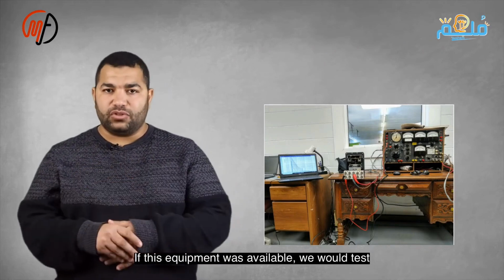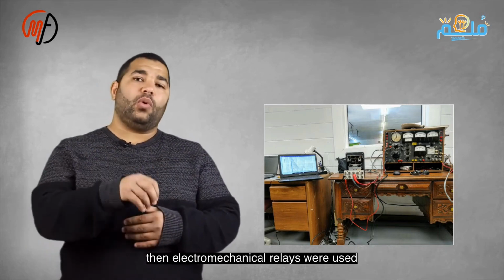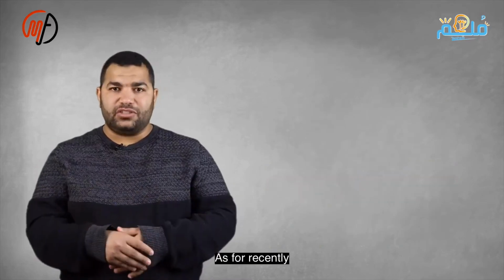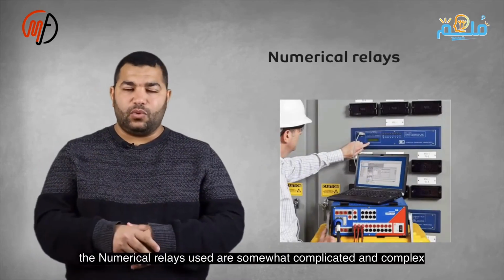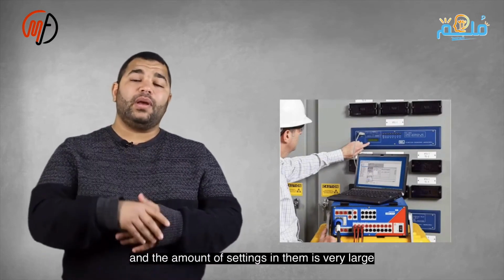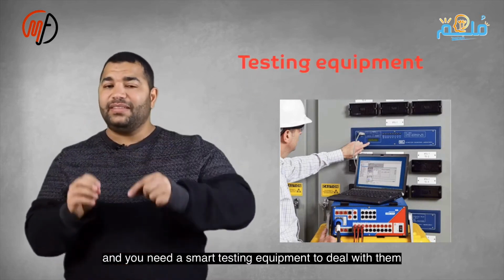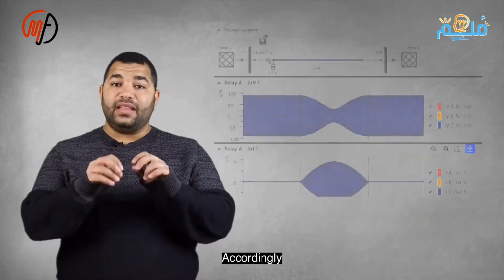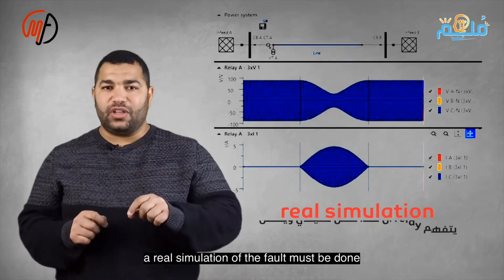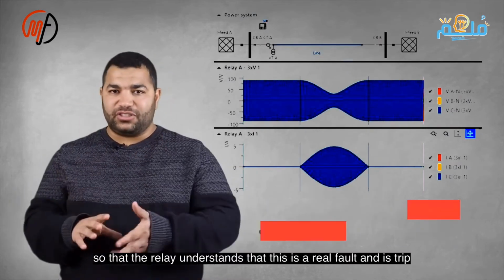Now, new numerical relays are smart and complex, requiring advanced testing equipment due to numerous settings. Real fault simulation is crucial for relays to recognize faults and disconnect. Without this, relays may stay energized. Engineers unaware of numerical relay stages might find relay behavior unpredictable. Testing electromechanical relays once took a day, but numerical relays now require days or weeks to test all logic. This complexity has led to specialized roles for testing engineers.